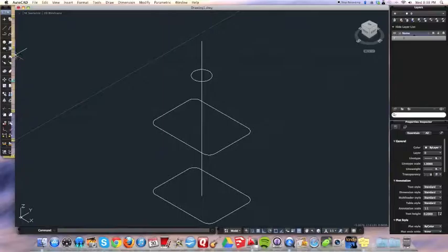Alright, I'm going to make one more. I'll make it on the top this time. Okay, and we'll go twice as big. Let's just go 0.75. That was really too big. Split the difference. All right, and I'm going to make one copy of that because the cap itself needed to be copied. Enter, base point, pull down 1, enter.